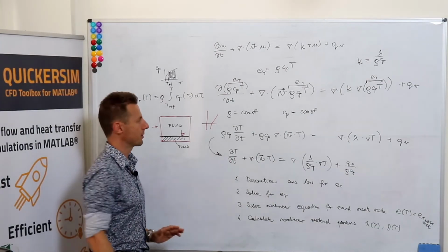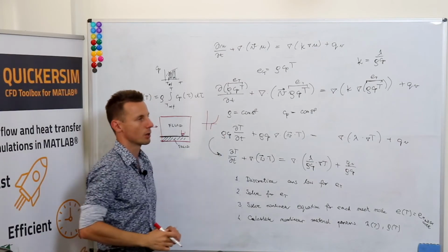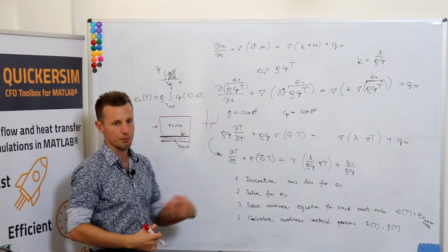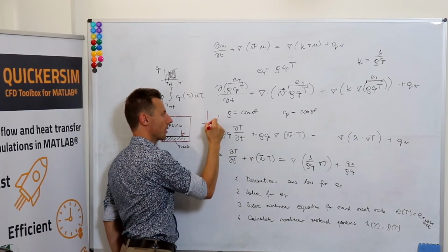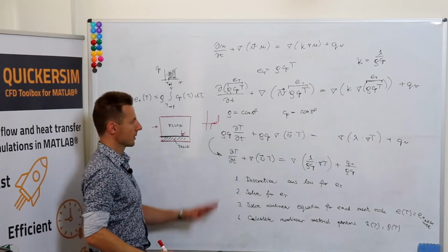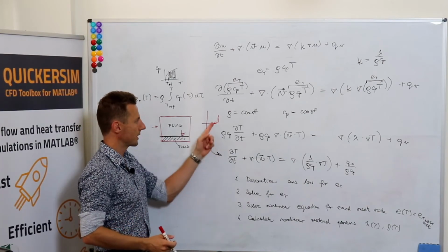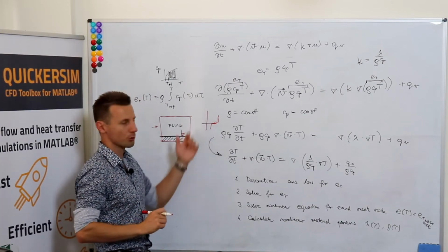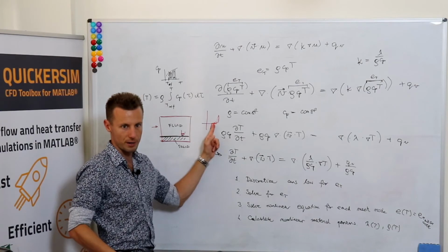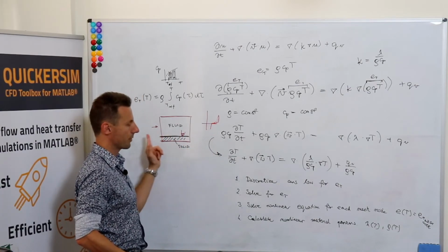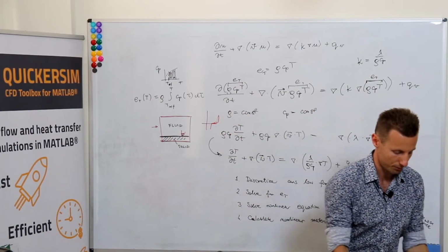What convection adds to the system? Convection makes the profile to be more convex. If you've got even stronger convection, then obviously the boundary layer will look like that. So you're increasing the gradient in the boundary layer, so close to the wall. That's why your fresh, hot fluid transports more energy and more easily to the interface. But certainly at the interface, no boundary condition, the heat transfer coefficients are the result of the simulation.